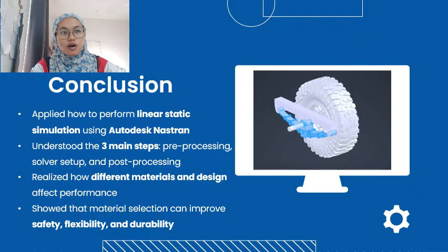And based on the result, we can conclude that the component is safe because the maximum stress that we get is below the yield strength. And finally, by trying different materials and designs, we can find ways to improve the performance of the leaf spring.